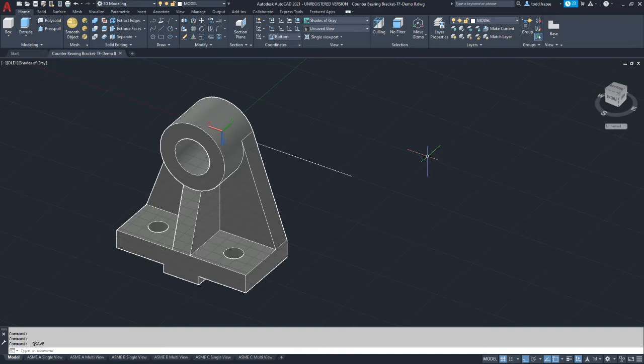experience, it still comes down to sequence and to have successful fillet transitions that you desire. The first two fillets we need to put in are the larger ones because we have two R9s that the smaller fillets need to wrap around. So it's possible you may have developed your model in a different method and may already have those features built in, but I chose not to.